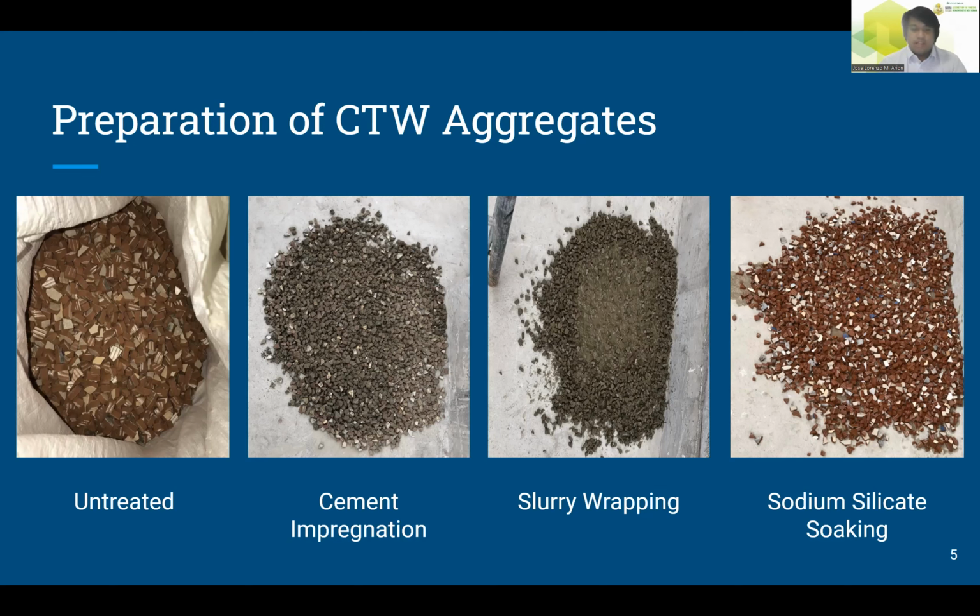As for the last treatment, sodium silicate soaking, it involves soaking the CTW in a mixture that had a ratio of 800 ml sodium silicate to 10 liters of water. And this was soaked in this mixture for 1 hour.